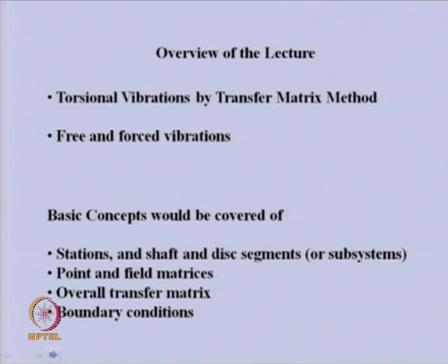Coming to the transfer matrix method or TMM, unlike in the previous cases like Newton's method, D'Alembert's principle, or any other method like Lagrange's equation or Hamilton's principle, in this particular case we try to derive the equations of some segment of the rotor system, like a shaft segment, disc segment or coupling segment.